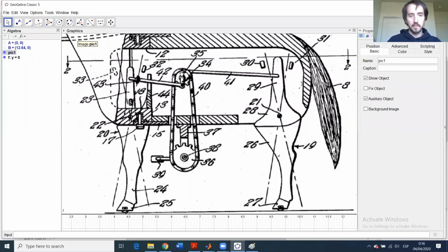Then you can see that this is the crank, and that we have two 4-bar mechanisms. One will be this one. This will be the first bar, second bar, and third bar. And finally, the fourth bar will be the floor, I mean the rest, the bar that joins the 2 points that are not moving, which are these two here.